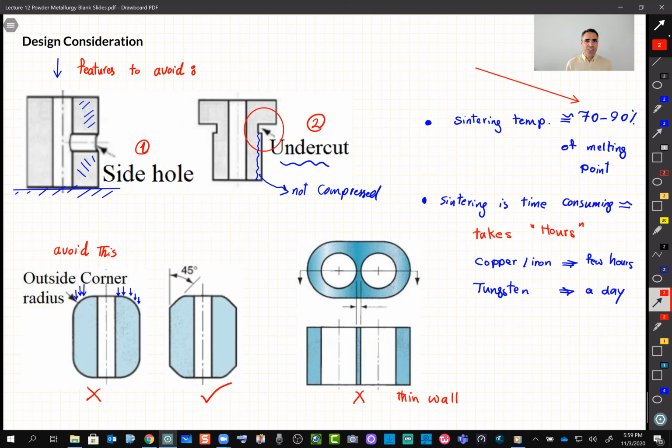So Jesse, as Panos mentioned, when you have two different metals with different melting temperatures, your base for the furnace is the one which has a lower melting temperature. That one is going to be the binding source. The other particles, for the high temperature metal, are not going to do anything. They're just going to stay as they are.